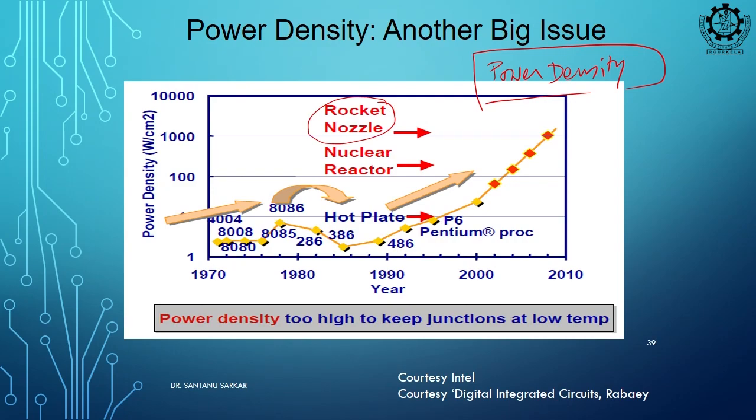Apart from performance variations or degradation, another risk is failure of the IC because of the heat density. So, this becomes so critical that you need to keep the power within some boundary, or you have to make some arrangement for heat dissipation, a cooling fan or cooling liquid, something should be there.